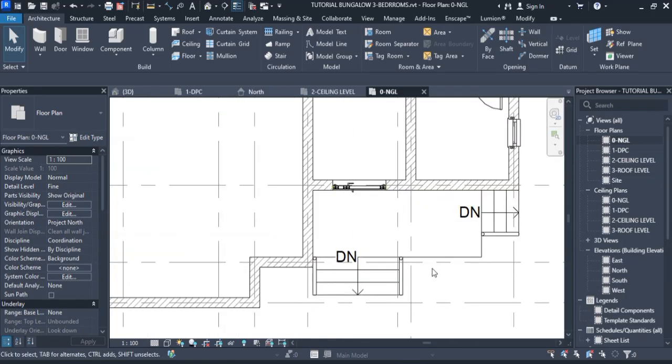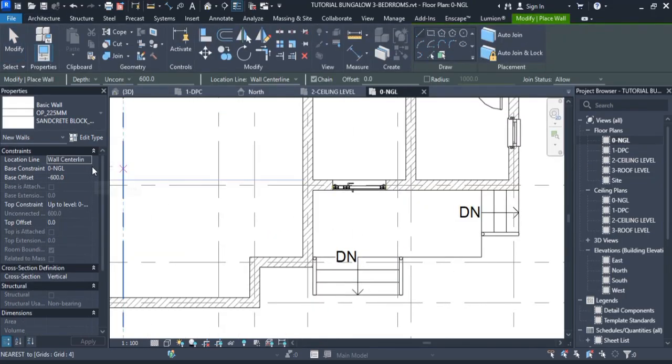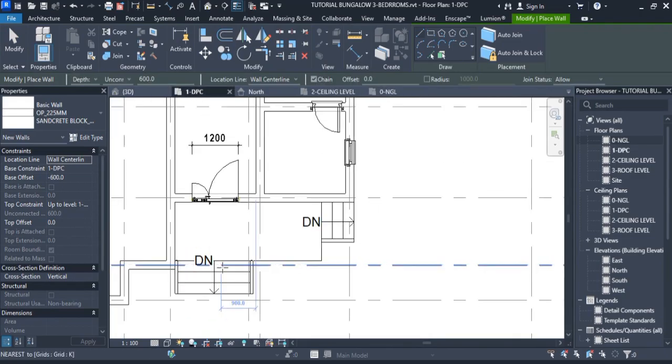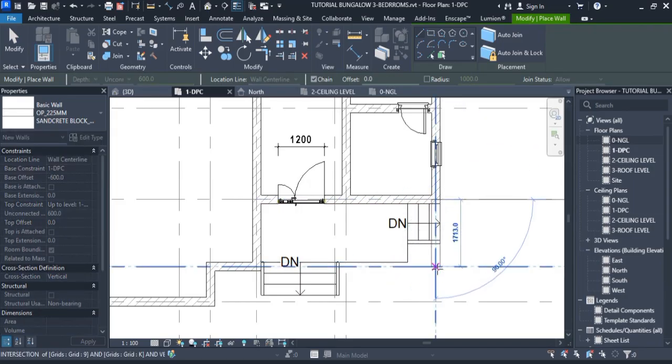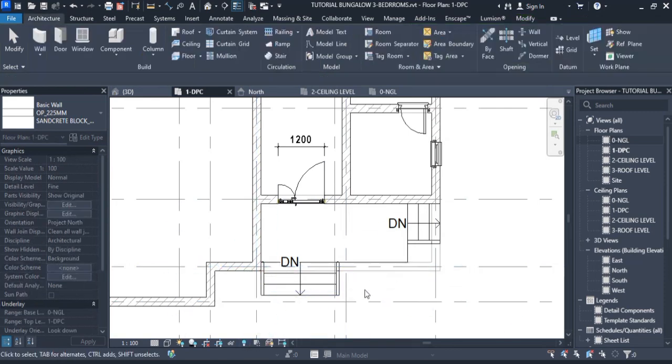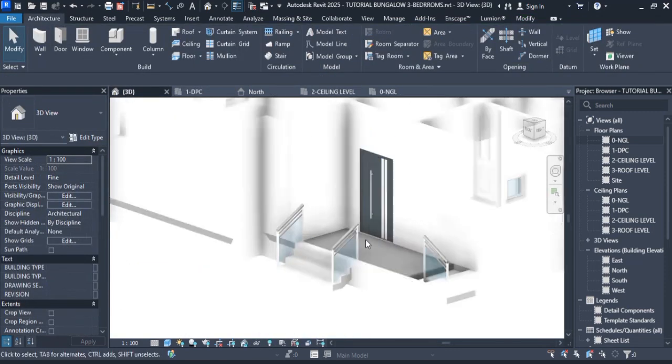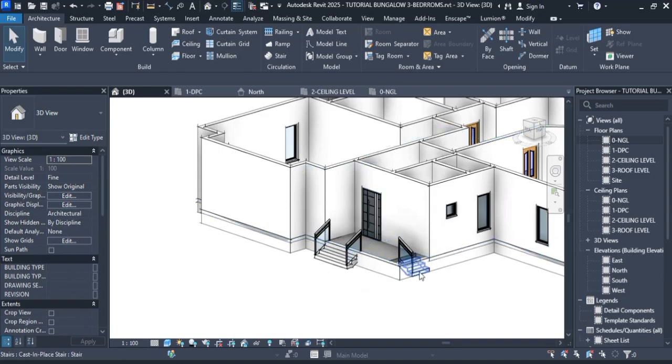I'm going to draw a wall, WA for wall, and then I'm going to change the depth. Remember, this wall is still in depth, so let me just draw the beam. So depth of 600 to this grid, then back to this place, so you kind of have our beam already set up.